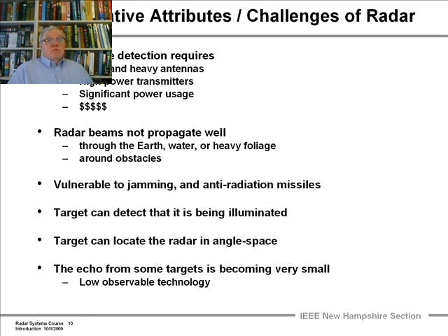There's no free lunch in the world. When you come with those positives, you're going to get that long-range detection, very far range. You need big antennas, big structural objects that are heavy, and you want a lot of power. Antenna size and power will give you that range. We'll see later when we discuss things quantitatively. And we use a lot of electrical power to generate the microwave power.